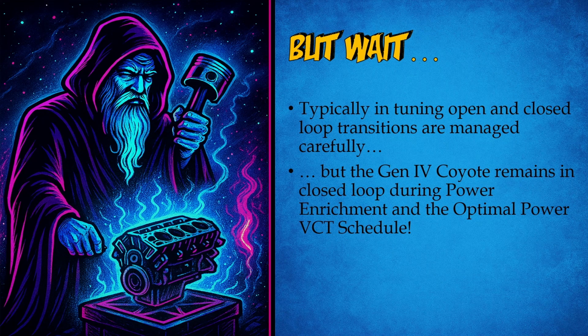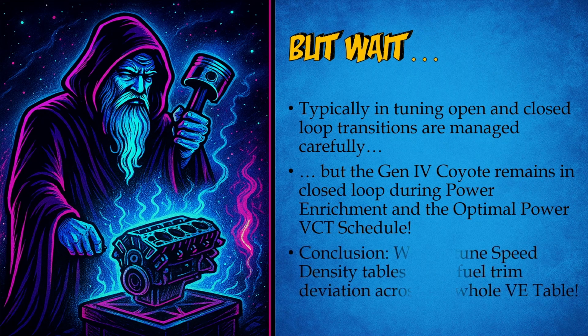So when we start getting aggressive with our torque tables, our power enrichment tables, and our spark tables, we begin advancing timing, we have to know that our calibration is spot on, right? And they're so lucky with this gen that because this power mode stays closed loop, that means, guess what? I don't necessarily have to do the MAP exercise from the previous 3 generations.